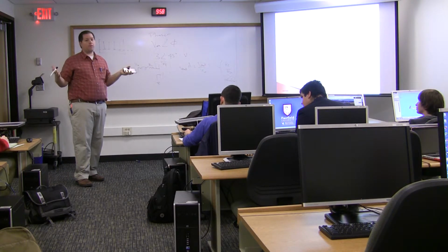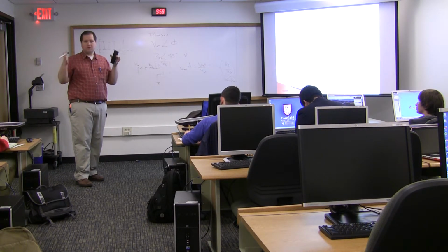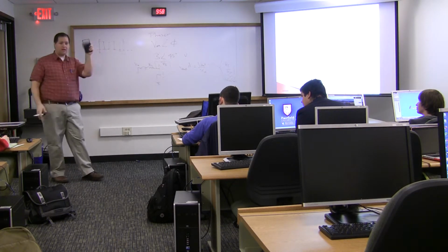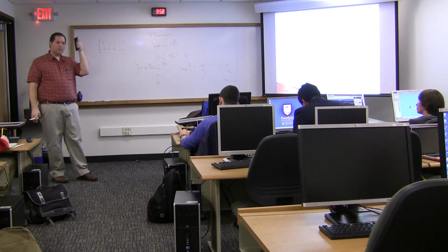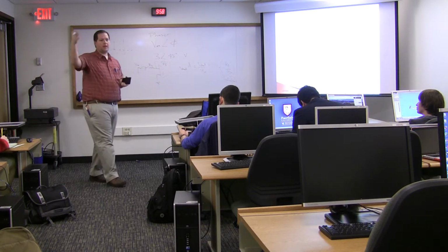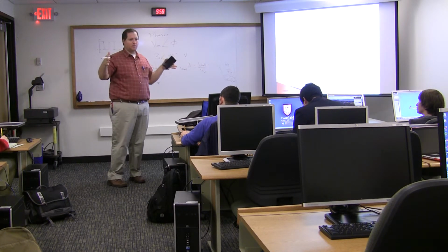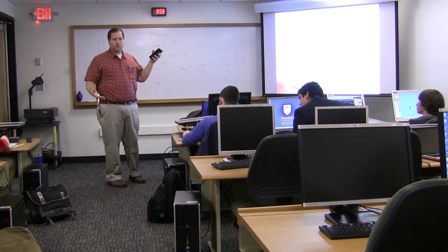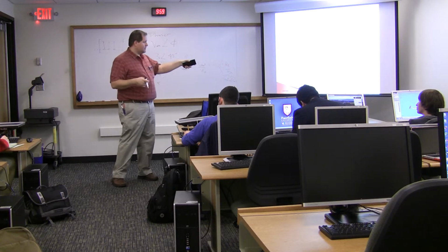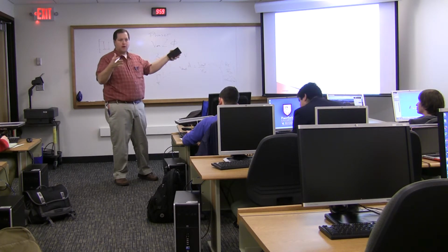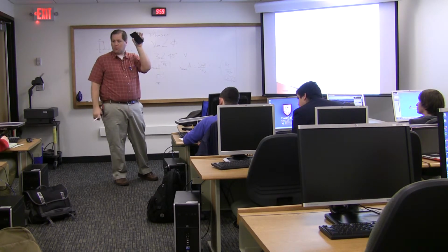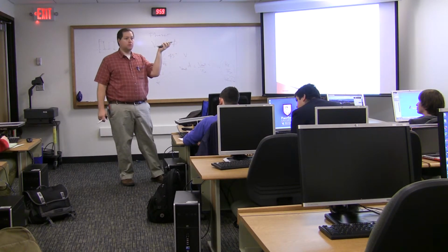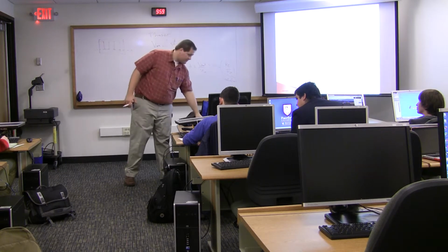When you're the electrical engineer, you say, well, my circuit will work like this for this whole range of frequencies. You can't make it work for all frequencies, but you can design to work over the range you're interested in. So if I'm building an audio amplifier for a phone, I can say humans can hear from 20 hertz to 20,000 hertz. As long as I can reproduce what I want over that range, great. Whatever they put in, I know the output will just be a multiple based on what I've designed. And that multiple is a gain, it gets louder.